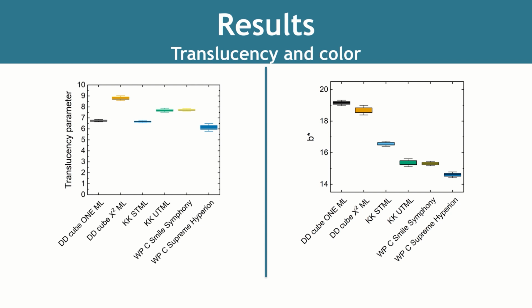The specimens for testing were prepared from the cross-section of the zirconia blank so that all layers were included in one single specimen. The figure to the left shows the measured translucency parameter for each material, and the translucency parameter is just a measure of translucency that's based on the color difference of the material over white and black backgrounds. The results that we saw are generally as expected based on the materials' respective yttria concentrations, with materials having a higher yttria content showing higher translucency, and vice versa.